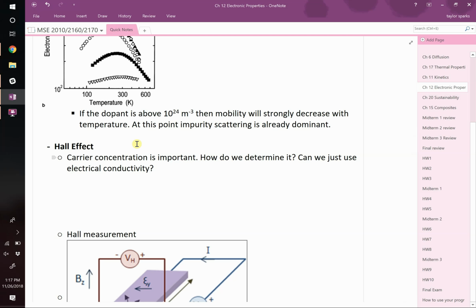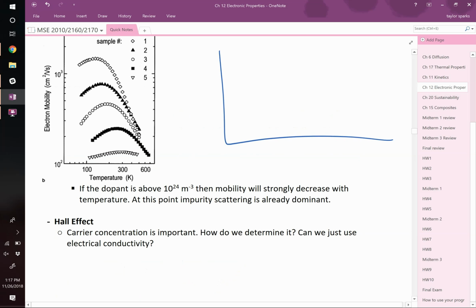We learned last chapter this. We said that if you were to take a concentration profile where you initially have some level at the surface and you heat it up, it's going to be non-steady state diffusion. So the concentration profile of your dopant species is going to look something like this. That means that your conductivity is changing as a function of depth. So maybe there's a minimum threshold that you have to get to. So you could tie back to the diffusion stuff that we learned about last chapter and say, I know the diffusion coefficient for this material. I know the temperature I'm taking it to. I know how deep I need it to go. I know exactly how long it has to be in the furnace to get that minimum conductivity. Right? It ties all these things together we've been learning about. Okay?